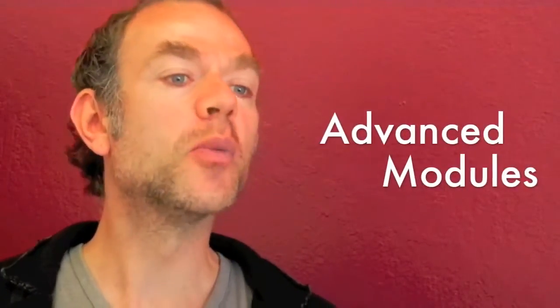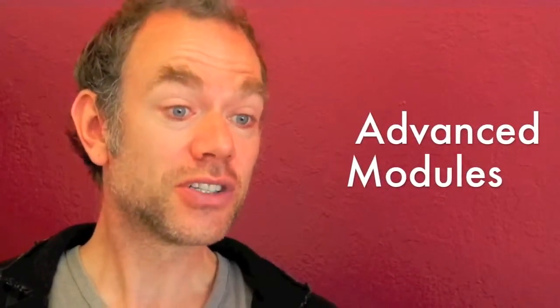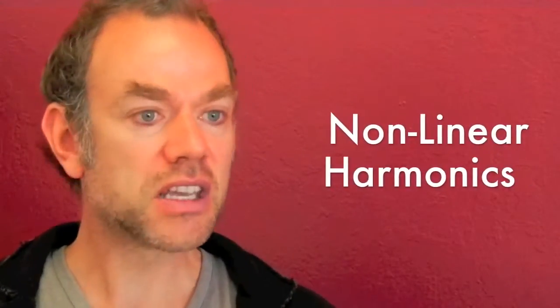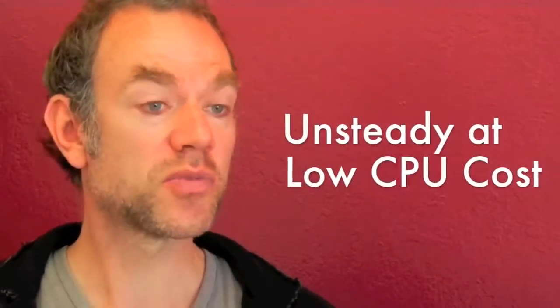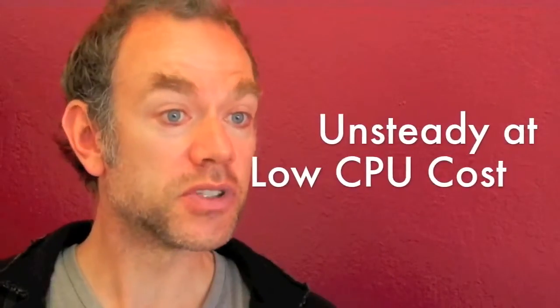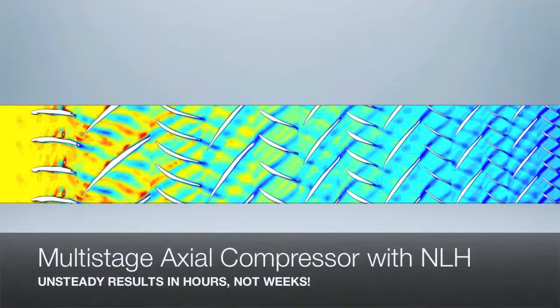An important module of the Fine Turbo solver, which generated a lot of interest over the last 5 years, is the Nonlinear Harmonics. So this is a technique that allows calculating unsteady flows in turbomachinery and rotor-stator interactions at totally affordable CPU cost. NUMECA integrated the pioneering nonlinear harmonic method into Fine Turbo.